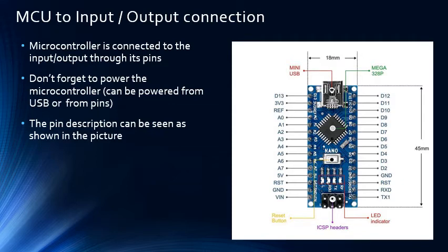You should give, let's say, 7 volts or 9 volts here, and then it will be regulated by the chip here, and it will provide 5 volts for the microcontroller. Or you can also apply a direct 5 volts by using this USB. So you connect using a typical USB cable to a power bank, and then the Arduino already gets some voltage. So the power supply can be applied from the USB or through this pin.